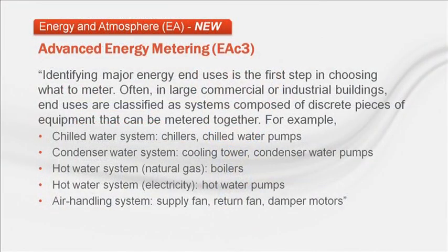Here's an excerpt from the LEED v4 reference guide that gives useful direction. It states that systems, rather than discrete pieces of equipment, may be metered to achieve this credit. So in this case, the chilled water system and perhaps the condenser water system should be metered.